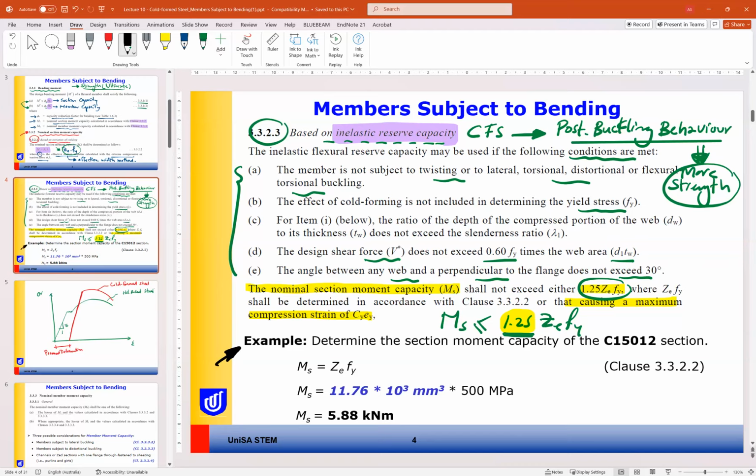So the section moment capacity for this C section, 150/12 section. Using the initiation of yielding clause, MS equals Z effective times F yield. From the table, Z effective of this section is 11.76 times 10 to the power 3 times F yield, for example 500 MPa for this type of section. So the section capacity is 5.88 kilonewton meter.